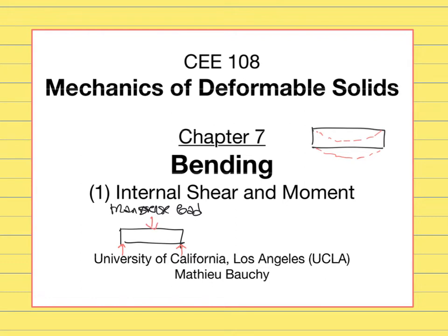In this case, those three shear loads are going to balance each other. The beam is going to be balanced, but because those shear loads are not applied at the same position, this will tend to bend the beam, and the beam will turn into a curve like this. So this is the first case.